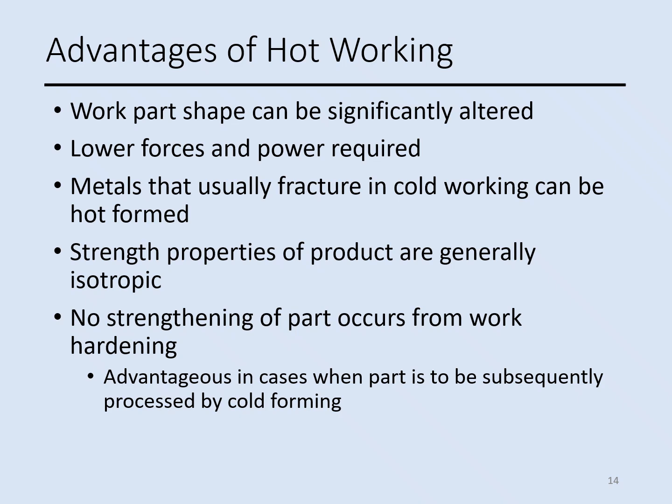Here are the advantages of a hot working process. The shape of the work part can be significantly changed. We would need lower force or lower power, and those metals that fracture at cold working can be processed in a hot forming process. And the strength of the workpiece becomes isotropic in the hot working process.